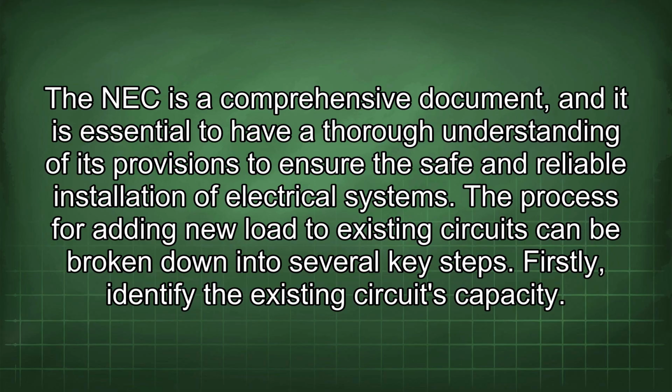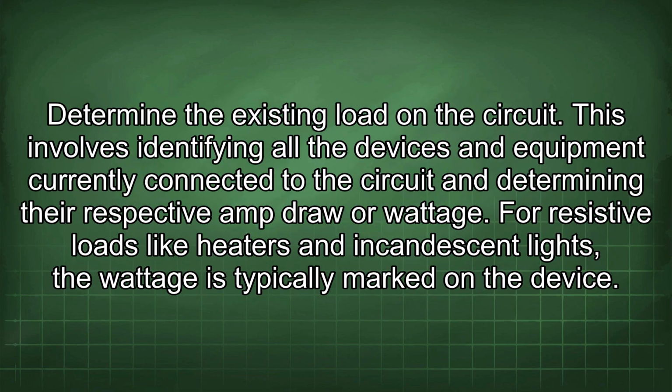The NEC is a comprehensive document, and it is essential to have a thorough understanding of its provisions to ensure the safe and reliable installation of electrical systems. The process for adding new load to existing circuits can be broken down into several key steps. Firstly, identify the existing circuit's capacity. Determine the existing load on the circuit. This involves identifying all the devices and equipment currently connected to the circuit and determining their respective amp draw or wattage. For resistive loads like heaters and incandescent lights, the wattage is typically marked on the device.